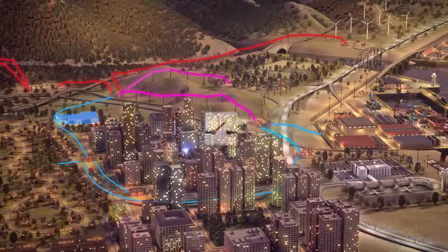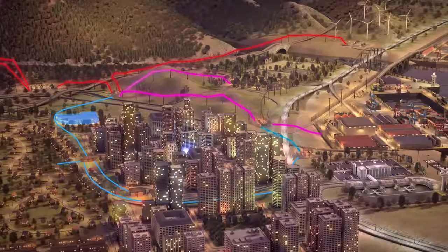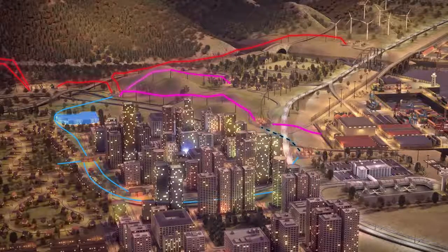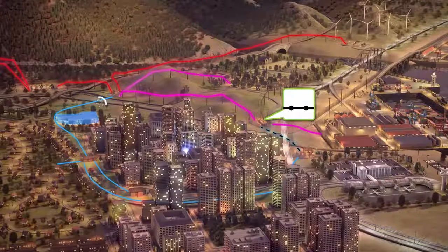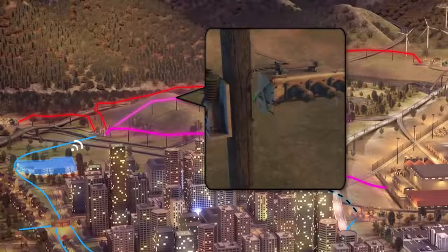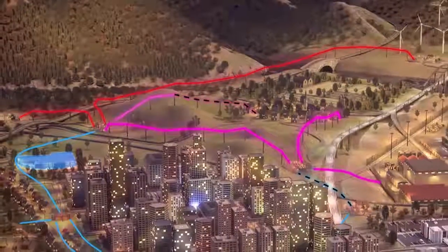The operator can now close the incoming switch to substation 2, reinstating the original supply route. The backfeed from substation 3 is no longer required, and so the SCADA operator can open its outgoing switch. With the load removed from the lower side of the network, the rural community outgoing switch from substation 2 is closed, creating a parallel circuit for the area. The final step for the SCADA operator is to reopen the GX switch to disable the backfeed to the rural community, restoring the standard operation of the whole network.